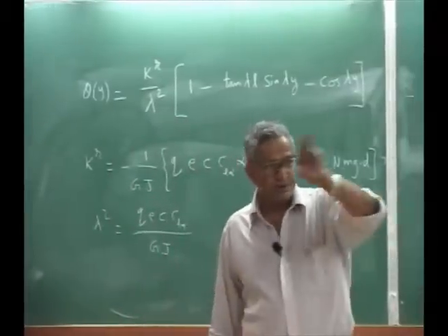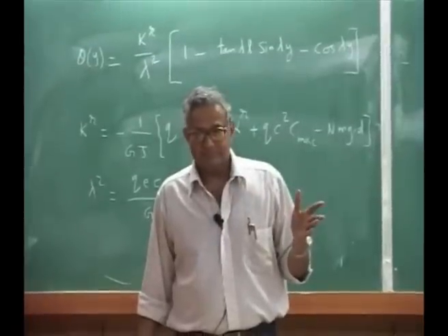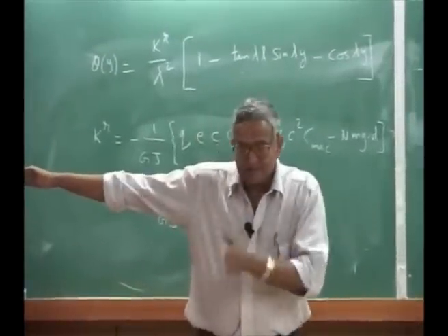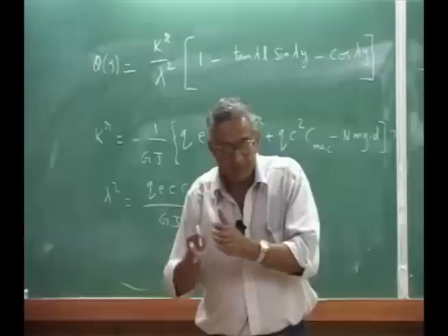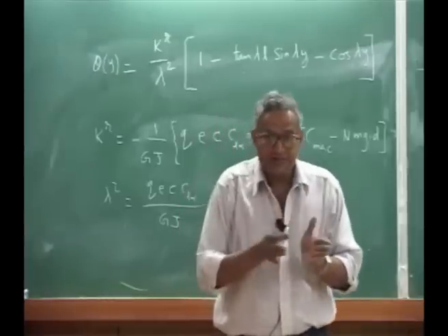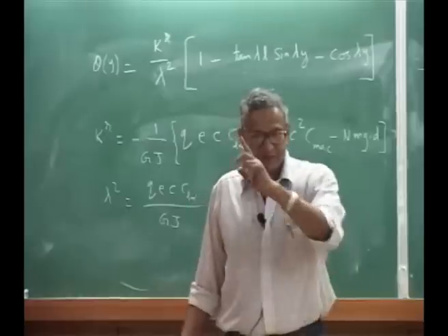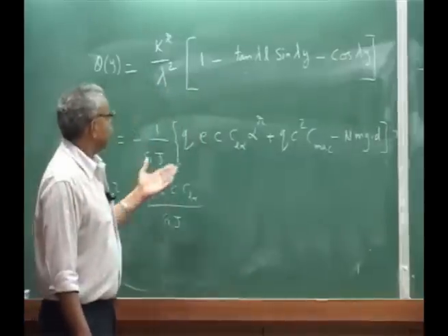But you are getting load distribution, but that is for designing for the bending problem. Please understand, because you take a wing, you want to design each section. Your load is changed. Therefore the bending moment, shear, everything will change. And then you design your new cross section. When you design your new cross section, your GJ is changed. Okay?